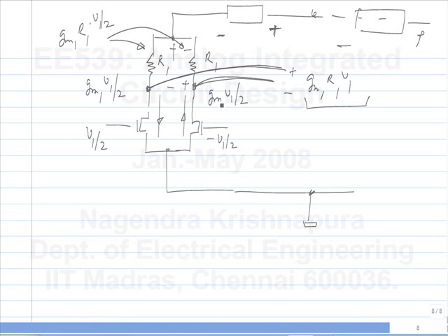You can think of it as you are supposed to measure a voltage across two wires. Normally you just specify one wire, assuming that the ground has no voltage across it. That is, there is a single point that is called ground. In reality you can't find it. That's why you have all these problems. So in a way, you are supplying the reference point for this signal along with the signal itself, like each wire is the reference point for the other wire. So you have both wires across which the signal is defined, and it's defined more accurately than before. So this is a very strong motivation for making fully differential circuits.